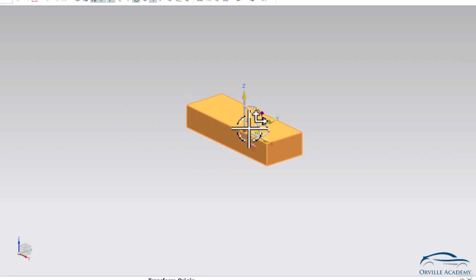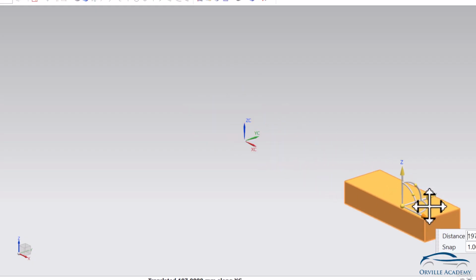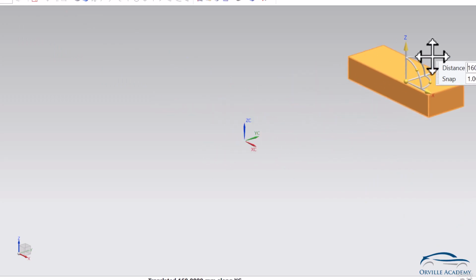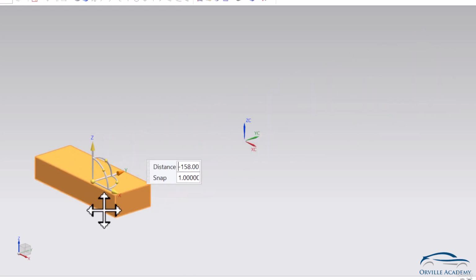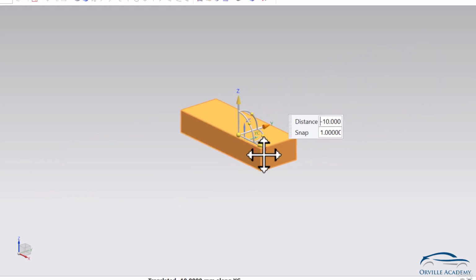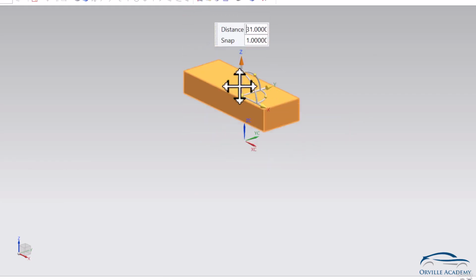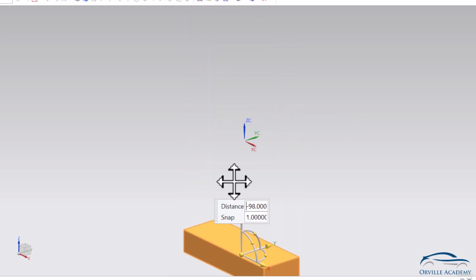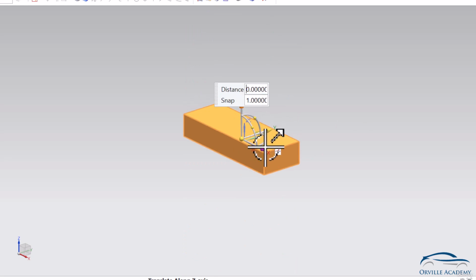As you can see here we have X direction, Y direction and Z direction. This object can be translated along the X direction. So this will be our first degree of freedom. In a similar manner, the same object can be translated along the Y direction. So that will be our second, or Y, degree of freedom. Again, in the same manner, the same object can be translated along the Z direction like this. So again, this will be our third degree of freedom. So in CAE, typically X means first degree of freedom, Y means second degree of freedom and Z means third degree of freedom. Same goes for the rotation also.